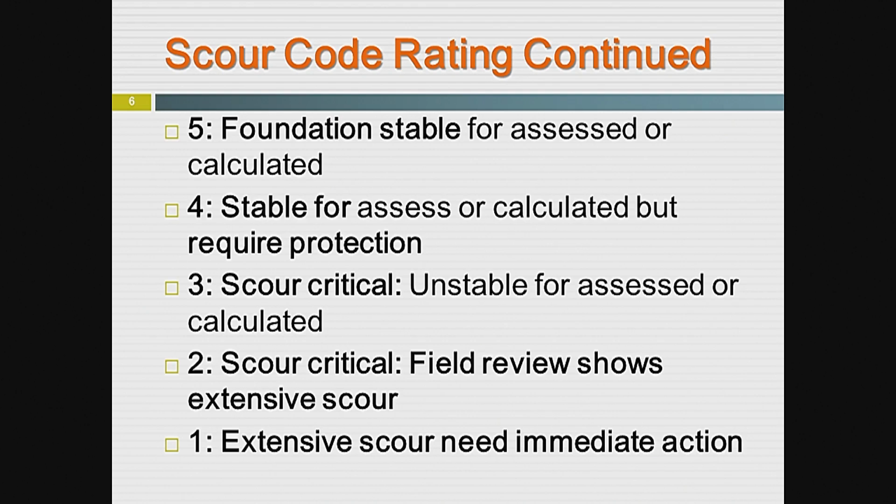We had 400 of these, and all these will go to substructure 2 and trigger a lot of things like I talked about: FHWA inspection at 12 months instead of 24, and then underwater at 12 months instead of 24 or 48 months, and critical follow-up, those things.